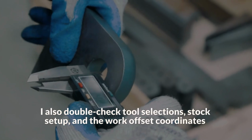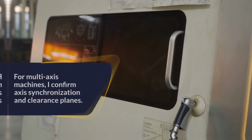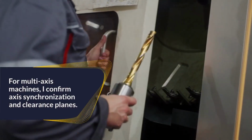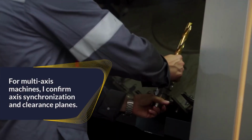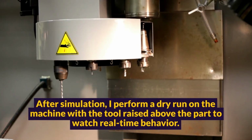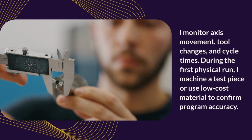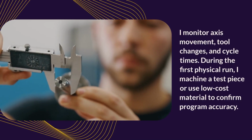I also double-check tool selections, stock setup, and the work offset coordinates. For multi-axis machines, I confirm axis synchronization and clearance planes. After simulation, I perform a dry run on the machine with the tool raised above the part to watch real-time behavior. I monitor axis movement, tool changes, and cycle times.